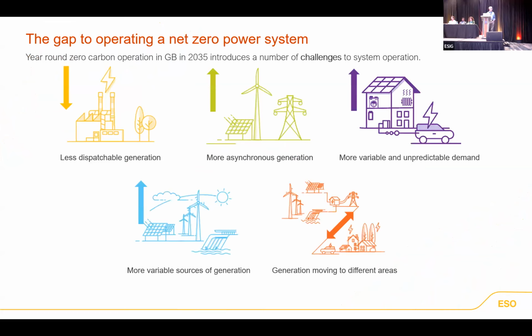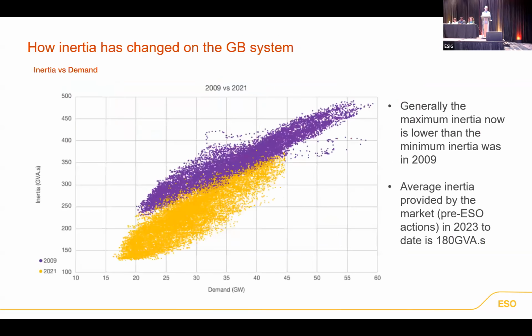As we know, nothing new on here. We are decarbonising very rapidly. As I said yesterday, 3 times this year we've been at 90% zero carbon. We've had 70% penetration of IBR on the network. So this is a real issue for us. We are on track that in just a year and a half from now, we will have 100% zero carbon generation for a few hours at least in 2025. So we need to be prepared for that. We need to make sure our control room operators are prepared and have the tools and awareness that they need.